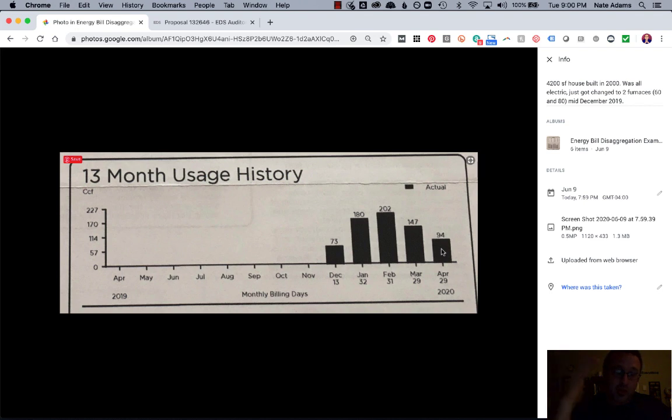That tells me that the house is fairly tight, and you'll oftentimes find that house is going to be in, say, the 700 to 1,000 square feet per ton ballpark for heating. And that was kind of where we got the house to. I'll record that in another video where I had to true this exact house, and it was a nightmare.